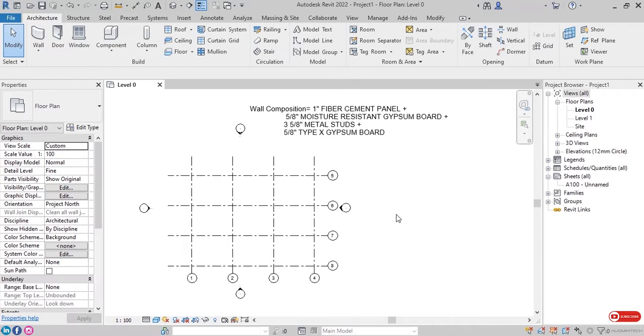If we are dealing with the exterior wall, then we must provide a composition which reflects the sun rays, so that the heat transfer from the exterior wall to the inside of our house will be reduced. We can consider our second example, the exterior wall of the building.